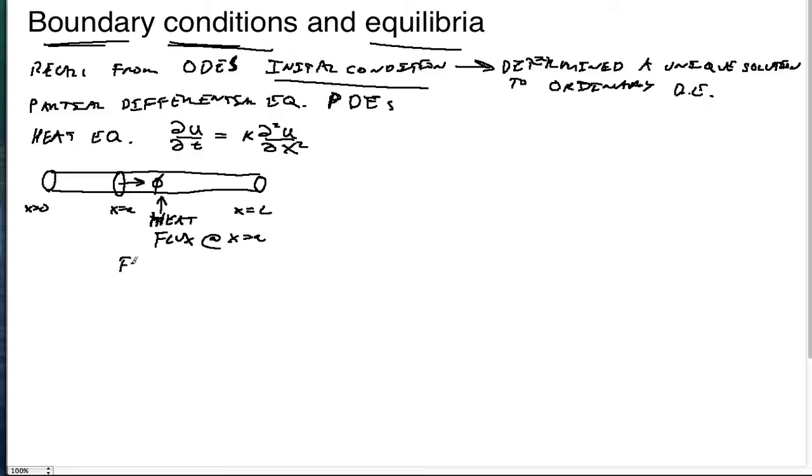And we use Fourier's law to state that the flux has to be equal to the negative spatial derivative of the temperature times this thermal conductivity constant, capital K0. All right, so we use that law, and that worked as long as we were inside. So this applies inside